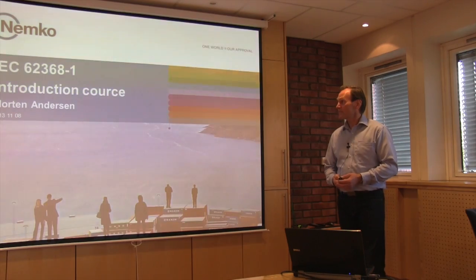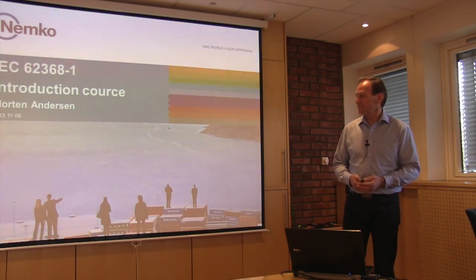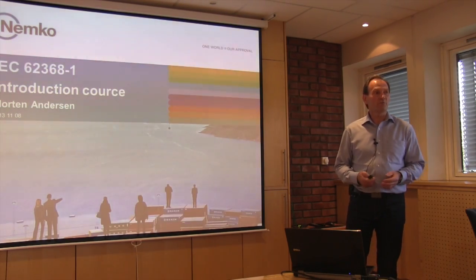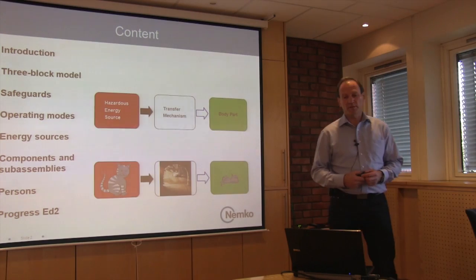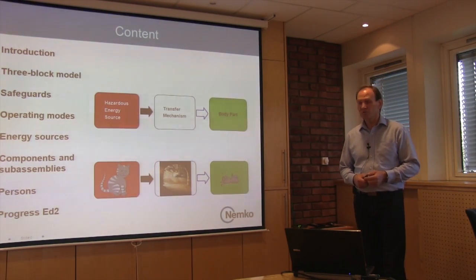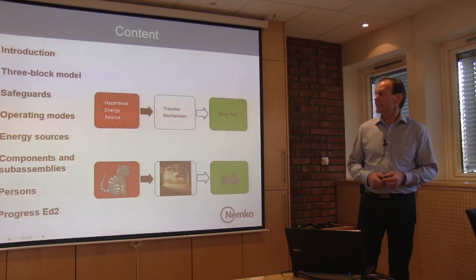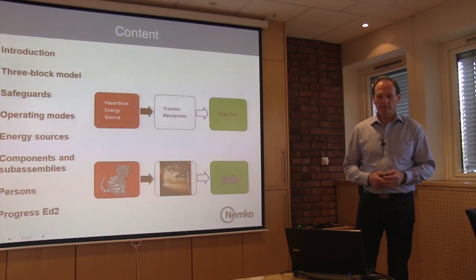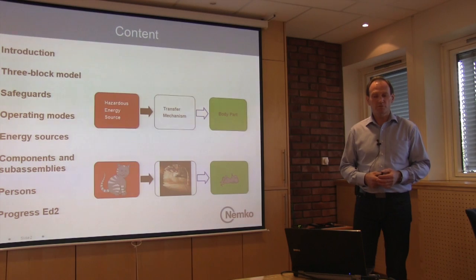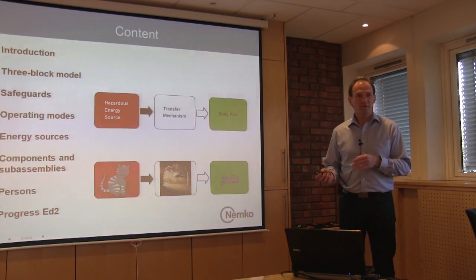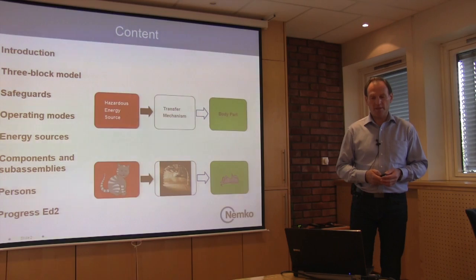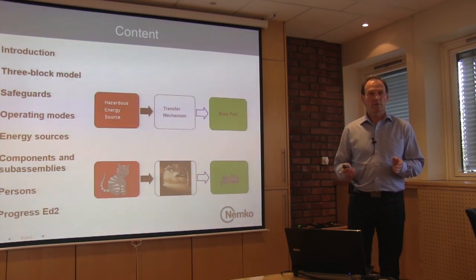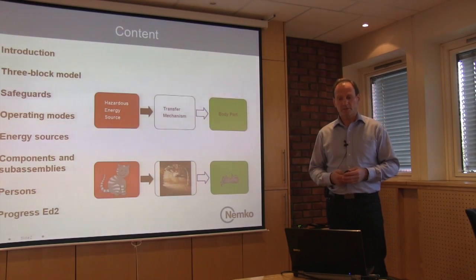So that is the hazard-based standard 62368-1, and this is a general introduction to the standard, not detailed in technical issues. So the content of this presentation is first a small introduction to the standard, the three-block model, safeguards, operating modes, energy sources, components and subassemblies related to 65 and 950 today, and also different classification of persons. And also at the end, I will explain a little bit about the progress of the second edition.